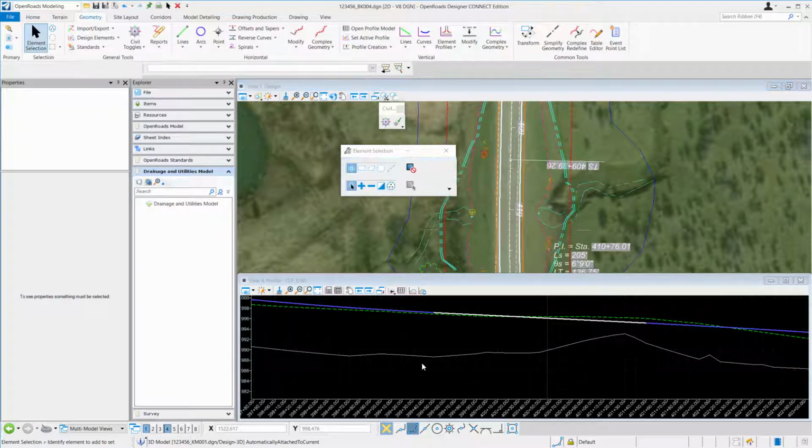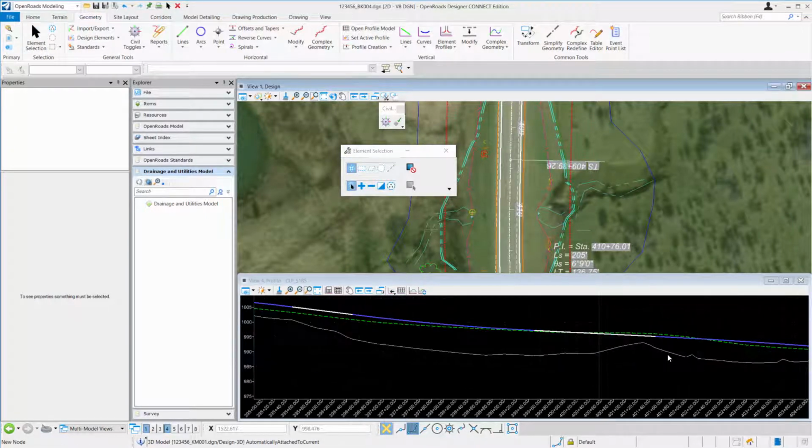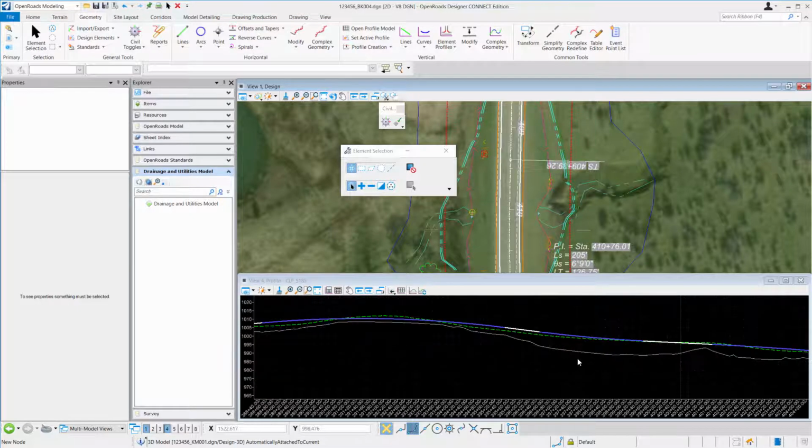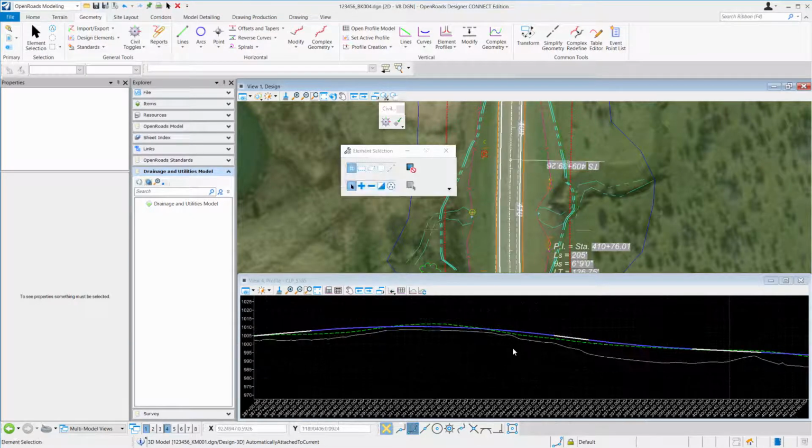Okay. So, this is just a demonstration. Maybe you don't want a ditch through your whole project, and maybe you just need certain areas. Then you could just draw in certain areas that you want and give them all names, and then you could add point controls in to control those given areas.